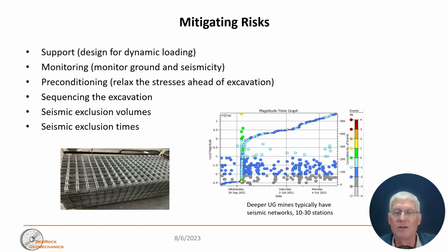Cables are longer than the dimension of the typical drive. So in a 5 by 5 meter drive, you can't put in a 10-meter bolt because it's stiff and straight, but you can put in a 10-meter cable bolt because cables are flexible. You grout them in. The support should be designed for dynamic loading. If a seismic event does come through, the shaking adds to the load, and there are ways to design support to handle that.